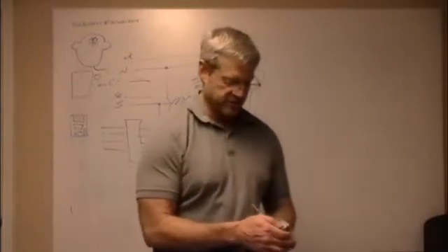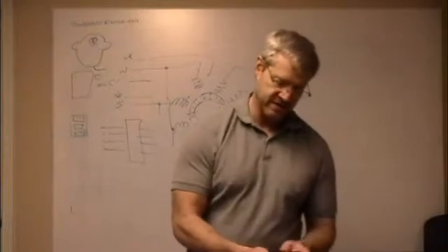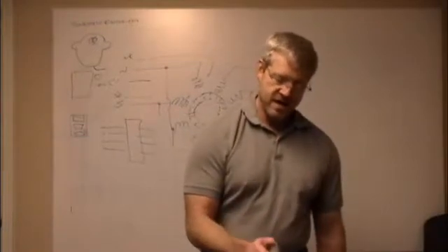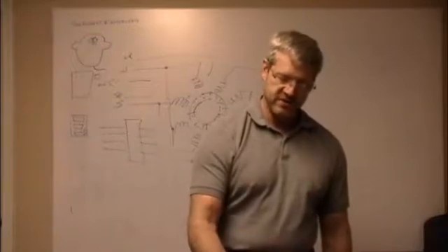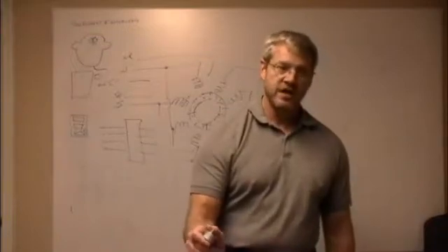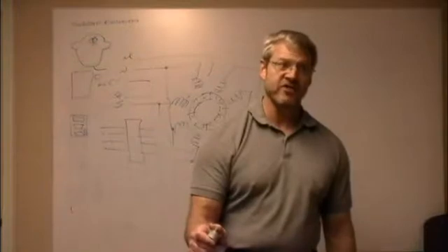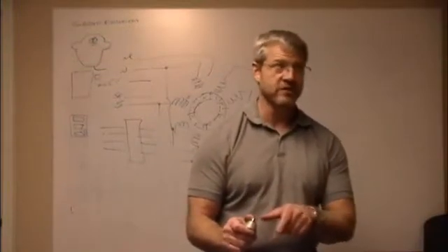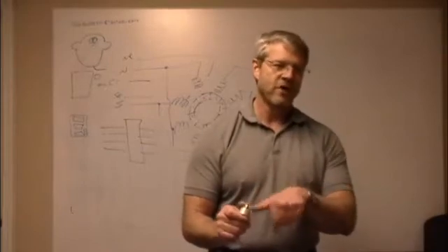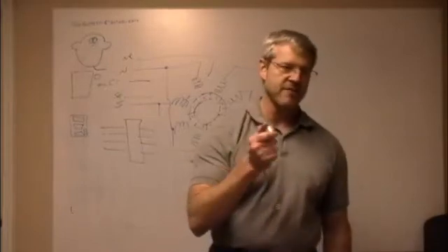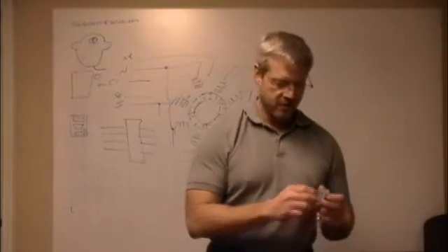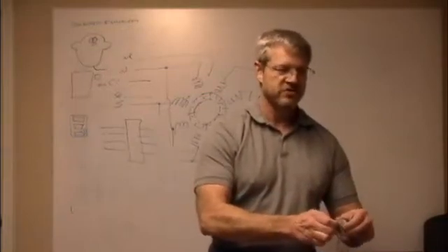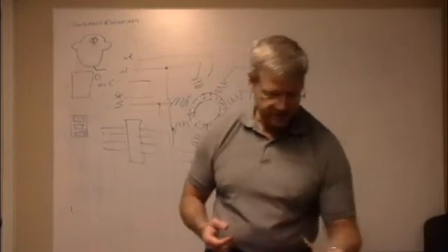And I was basically putting my thumb on it like this as an indicator for me to count turns and everything else, and watching it. And at least as far as the eyeball and the thumb feel goes, it was stopping in the same position every time. I'd go forward 4,000 steps, 1, 2 turns. Now go back, 1, 2 turns. Best I could tell, it was stopping in the exact same position every time. Within the slop, I mean, you can feel there's a little bit of play. There's slop in there. There's backlash.